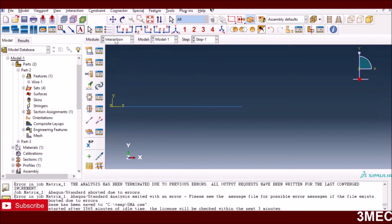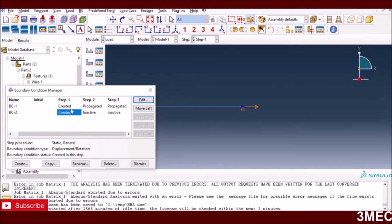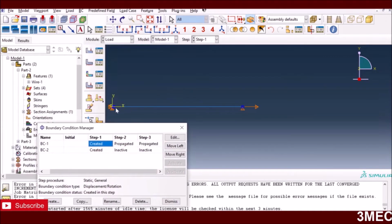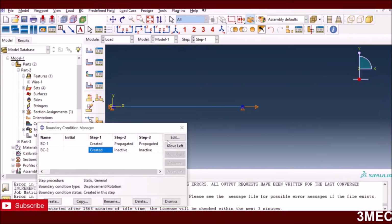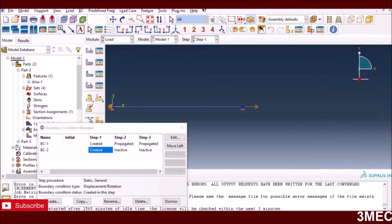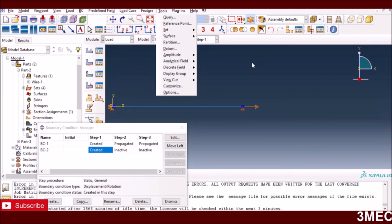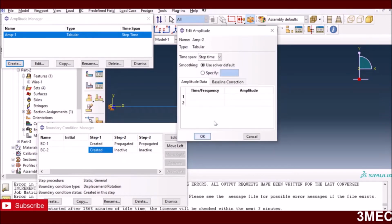Then I go to the loadings, and the loading is very much the same as they had in their experiments. I have no forces, but it was a displacement control test. This is one end of the matrix material, and this is the other end. I have fixed everything on one side, while on the other side I only let it move in the horizontal direction with this displacement, using an amplitude of amp1. And what is this amplitude? Again, you can create an amplitude directly there, or you can create it from here. You can create an amplitude, choose tabular, and then give the values here.